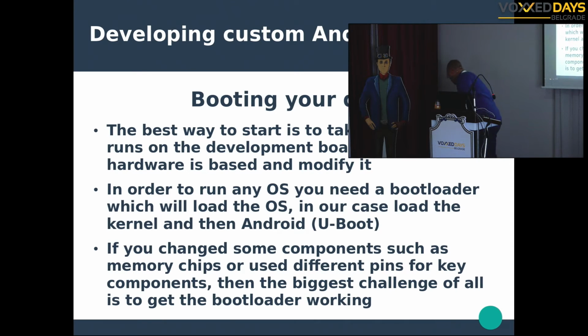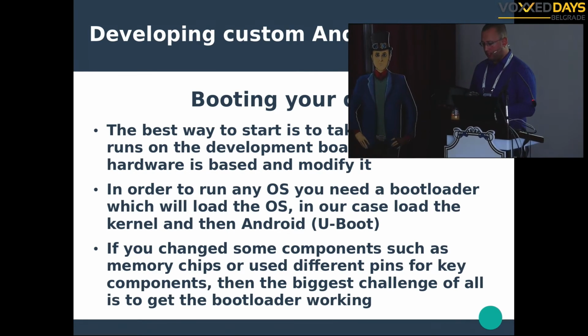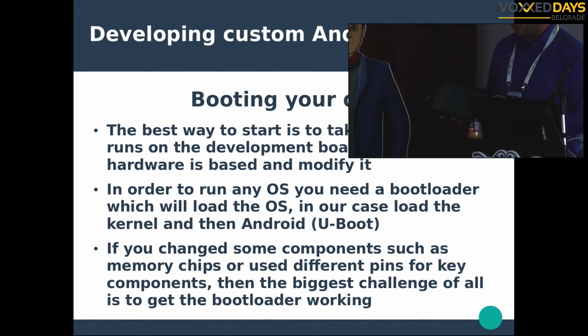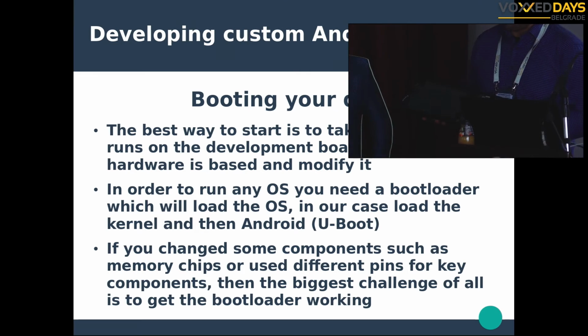So even with this board, as you have the LCD and everything else. For example, if this is your custom device, it's not a development board, and you try to run your bootloader, you upload it with some ways that you prepared, you will get nothing. That's why the tricky part is to run it, because you do not have a lot of debugging tools. For example, one of the things that we used while bootloading was one LED diode on the board, so we used that as a debugging tool.